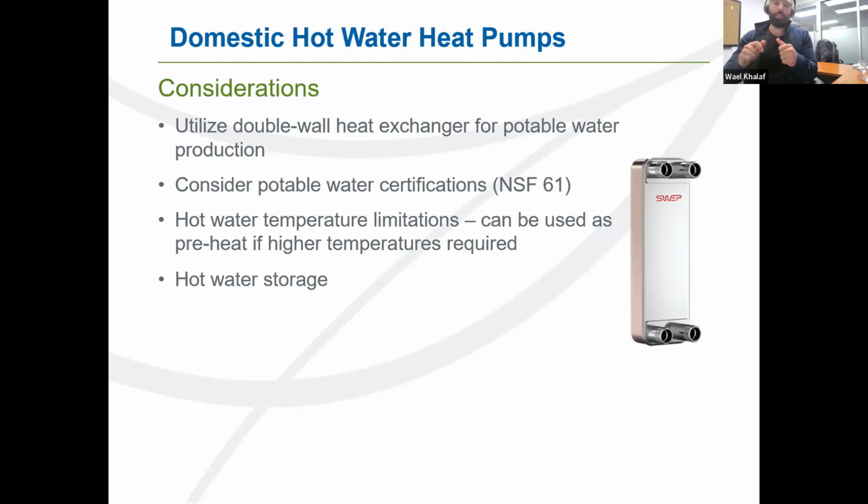If you want to achieve your instantaneous load like you do with an instantaneous water heater using heat pumps, there's in no way you will ever be able to make financial sense of that application. Using heat pumps for domestic hot water production must be coupled with domestic hot water storage tanks in order for the application to make sense technology wise and financial wise.